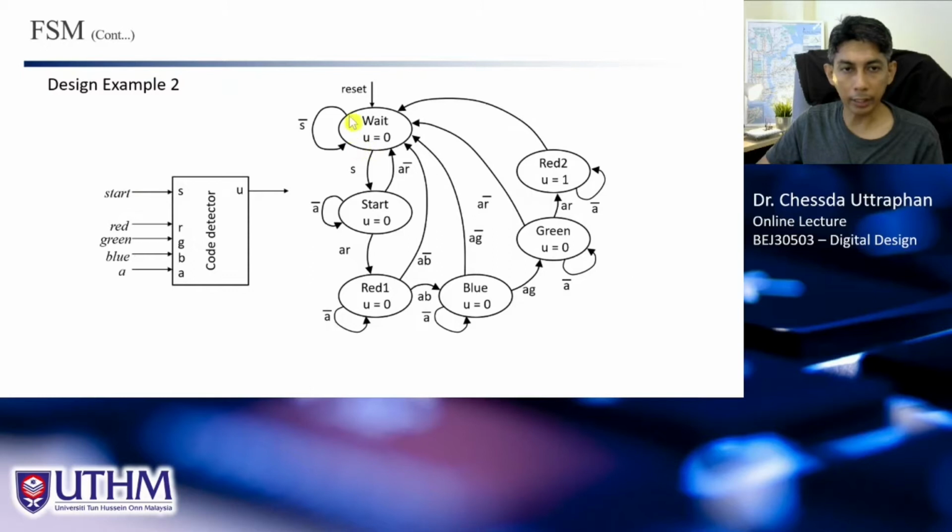If s, this is the s signal, equals 0, it means the start button is not pressed, so we will always stay in this wait state until s equals 1. In the wait state, the other signals are don't care; we only look at the signal s, so we don't have any other input for this state.